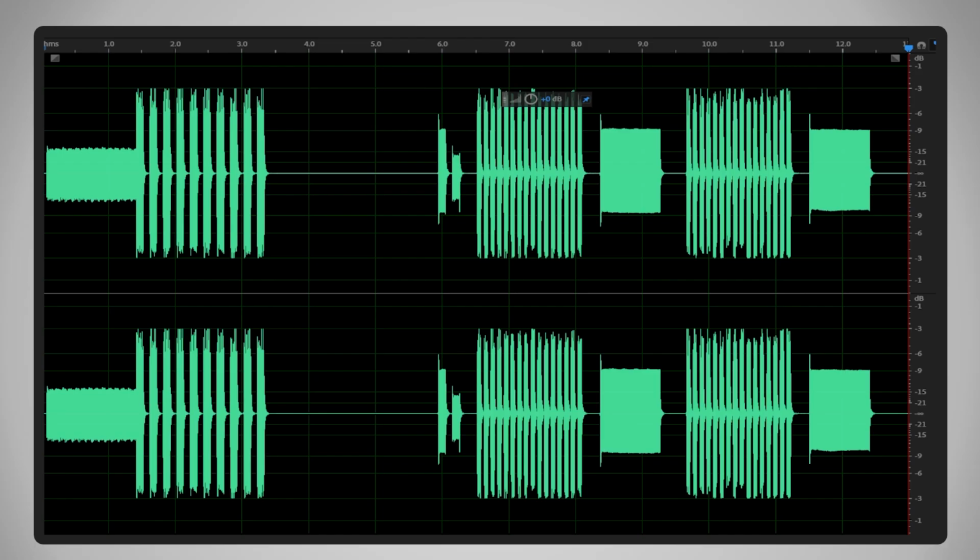The first part is the panel dialing 10 digits for the phone number. After that, you hear the radio respond with the contact ID handshake. After the handshake, the panel responds with the data dump. Finally, the radio responds with the signal that lets the panel know it has received the data, and that's called a kiss-off. If any part of this transmission fails, that is considered a communication failure.